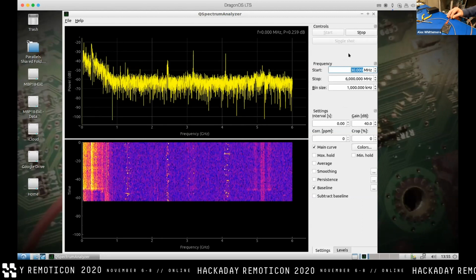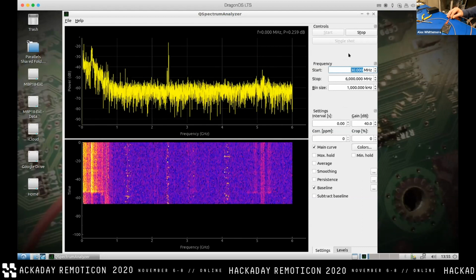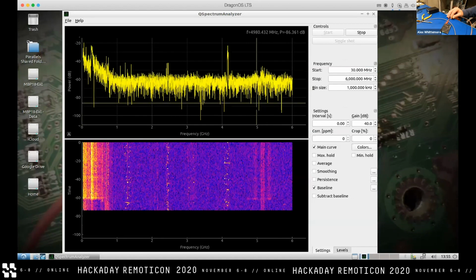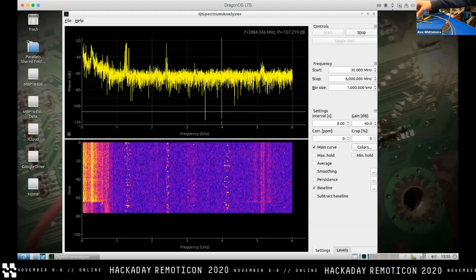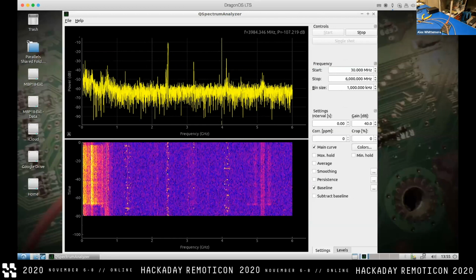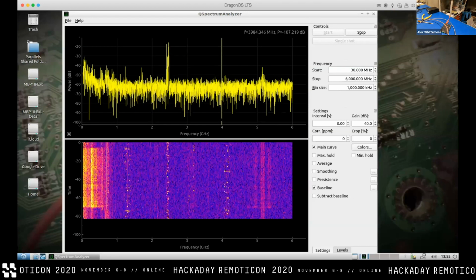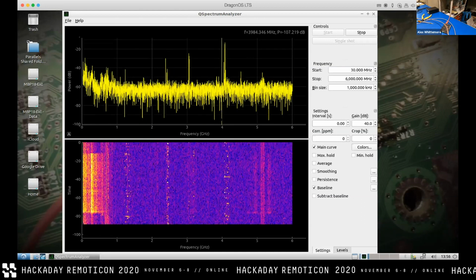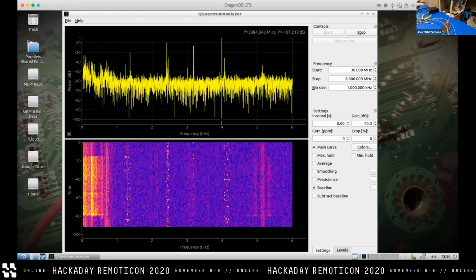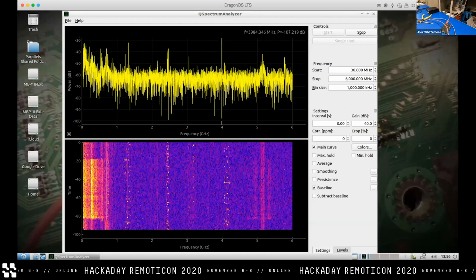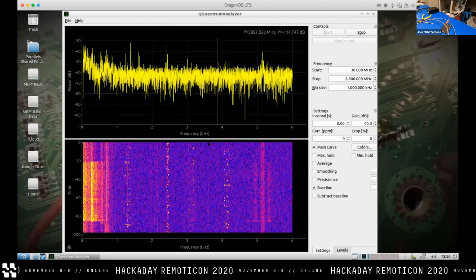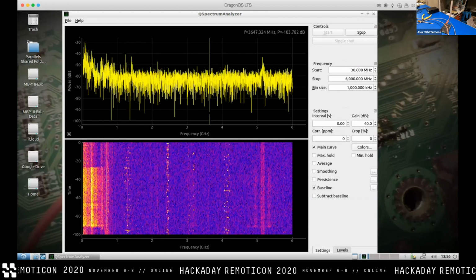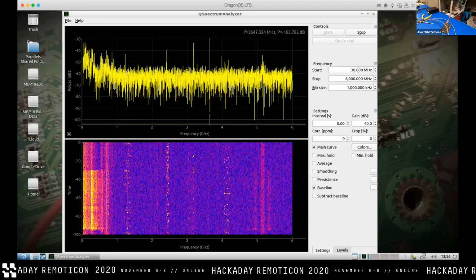I honestly don't know what that 4 and change gigahertz line we're seeing in this region is, and so on and so forth. But you can imagine that if you were in an at all clean RF environment and you were just knocking around your board with a near-field probe trying to find this stuff, you will probably have a relatively easy time of it with the HackRF and HackRF sweep enabled. And you can do this with the RTL-SDR. It's just a lot slower and less convenient. So all sorts of options.